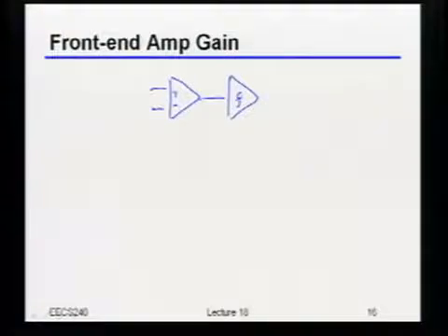If you notice in your project, I didn't tell you anything about what the gain of that preamp should be. In fact, I claim it's totally up to you to decide what that gain is. So if you come and ask me, what is the gain? I'll say, I don't know, I don't care. It's up to you to figure out. Okay? But that's not to say that obviously it's a totally free variable. So if you look in the project, I told you what the input amplitude is. I just assumed that I knew what the transmitter was, and I told you that input amplitude. And I actually also told you what the offset of the comparator is.